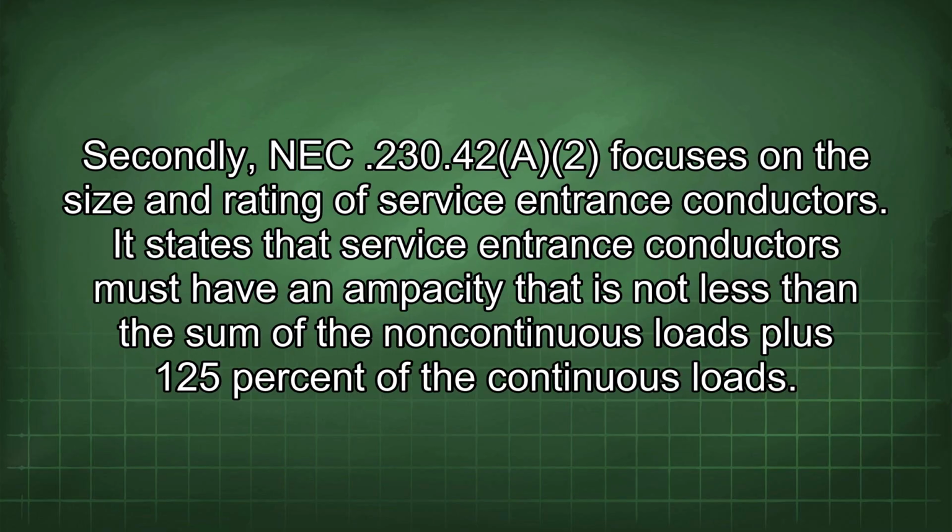Secondly, NEC 230.42(A)(2) focuses on the size and rating of service entrance conductors. It states that service entrance conductors must have an ampacity that is not less than the sum of the non-continuous loads plus 125% of the continuous loads.